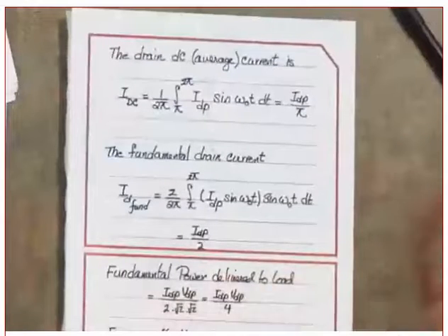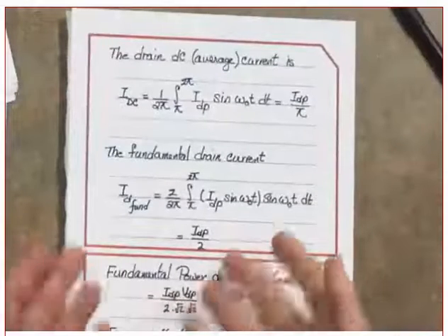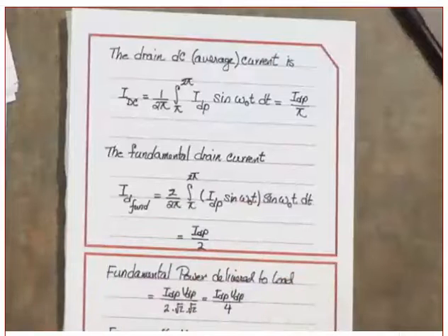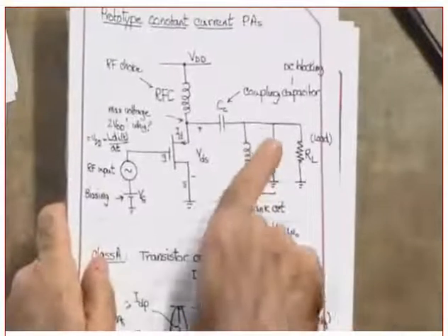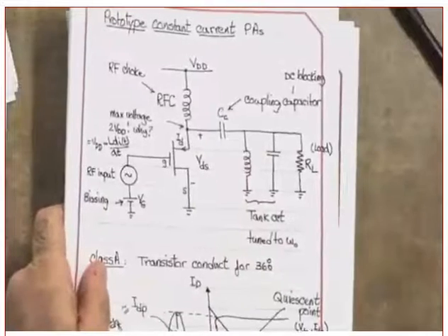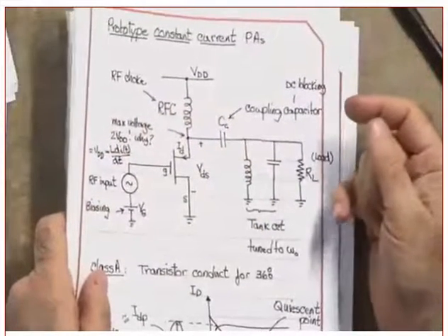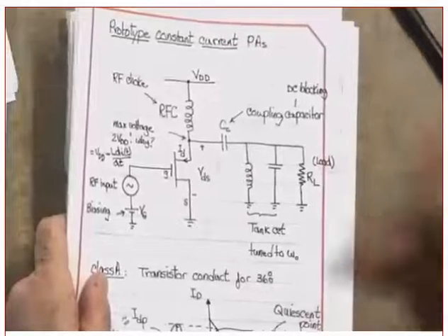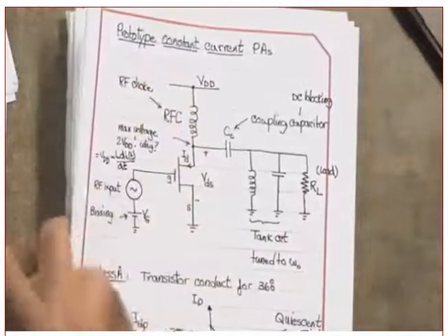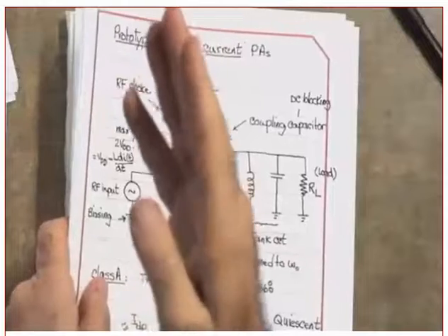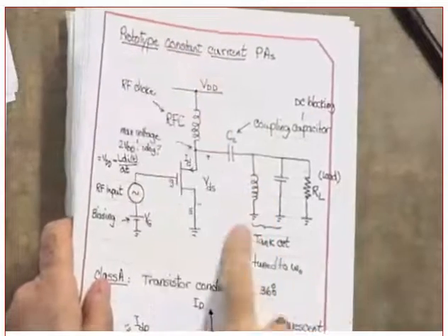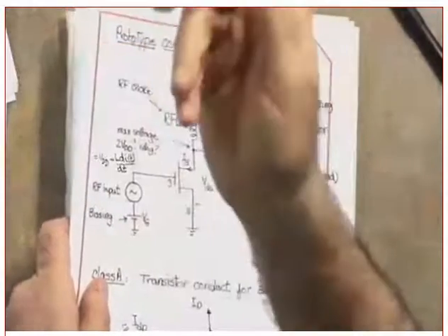Question, before I continue. What will happen to the second harmonic, third harmonic, fourth harmonic? Now, do we need the tank circuit or not? We need the tank circuit. That tank circuit needs to be tuned to omega naught, which means at all the other harmonics, I want the tank circuit to behave closely to a short circuit. Notice I said closely. Why? Because this is a tank circuit tuned at a singular frequency, which is the fundamental.